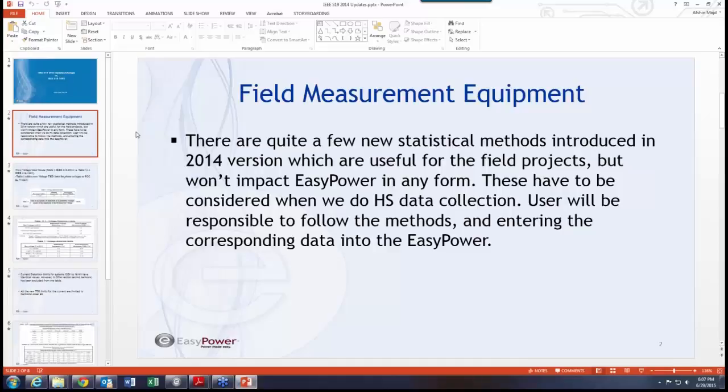For harmonics, you have to really make good assumptions at some point. I gave an example a few minutes back: you get the data sheet from the turbine manufacturer or from a photovoltaic manufacturer or from a VFD manufacturer. You do the same type of test and measurement in your field, and your values are not entirely in line with the data sheet from the manufacturer.